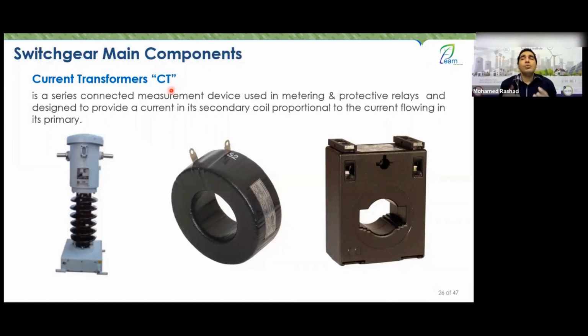Right? So what do I do? I use a current transformer in the middle, which reduces the current from, say, 3000 amperes to 1 ampere. How do I know that the primary current is now 3000 amperes? Well, these devices, engineers, are either digital or analog. In both cases, there is something like a compensation factor.